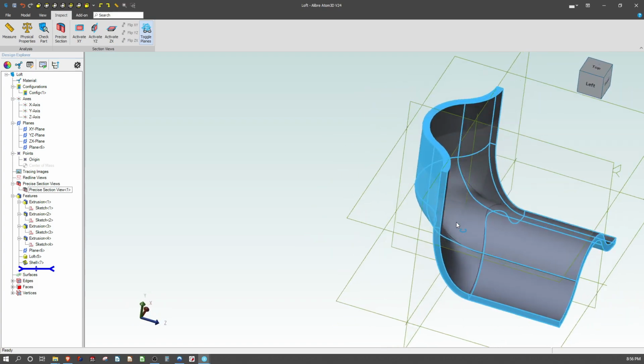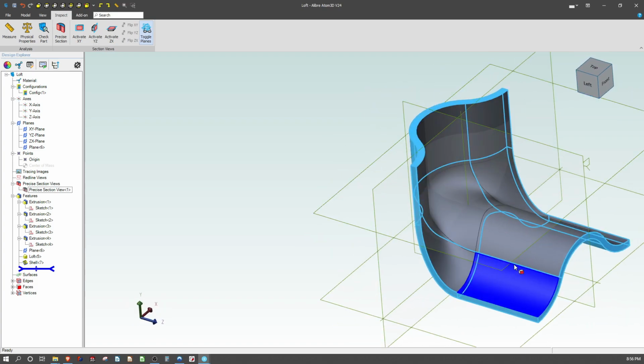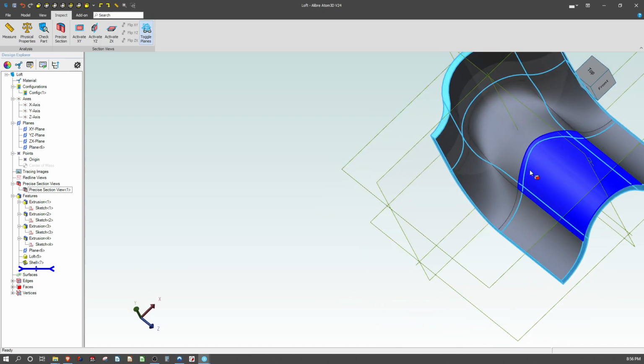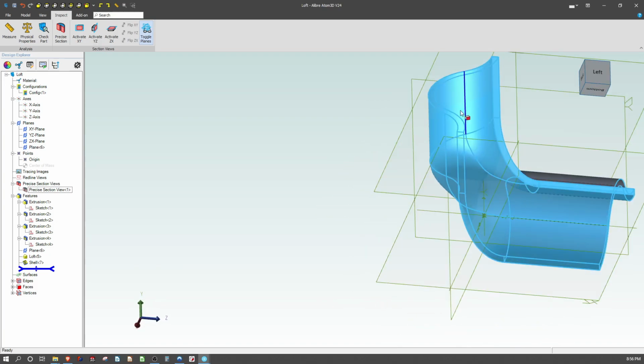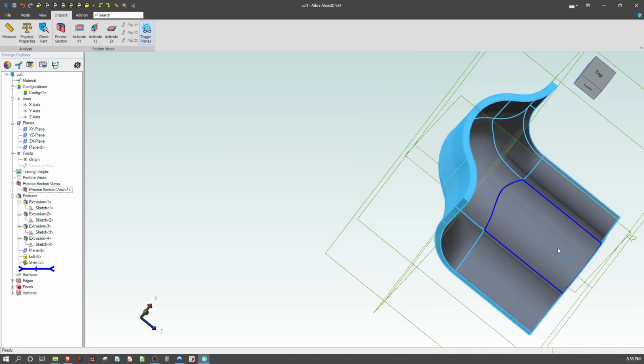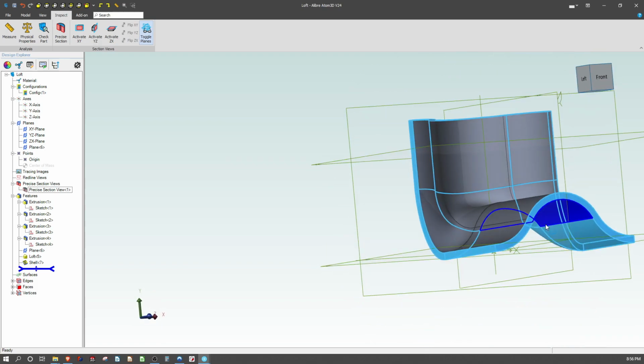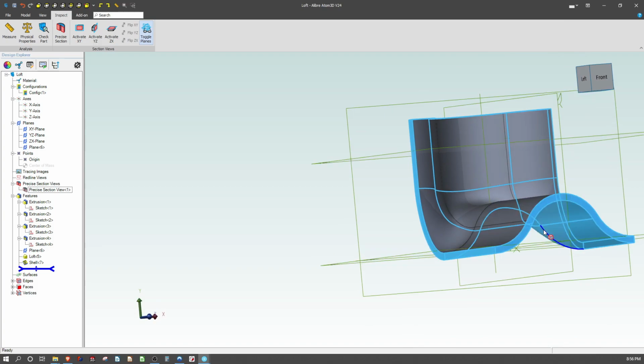And of course, since we assumed our interfaces were the profile that we wanted, and the variation in thickness caused an error on these outer faces, then those are the ones that we've made thick and then shelled out to the right thickness. So shelling is for more than just making things hollow, right? This is for making things a consistent thickness as well. And it's an easy and nice way to work with Alibre, in my opinion.